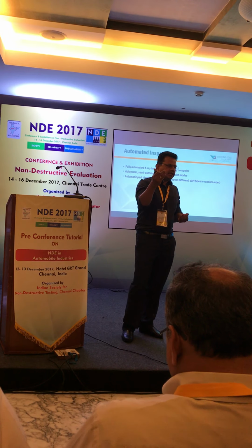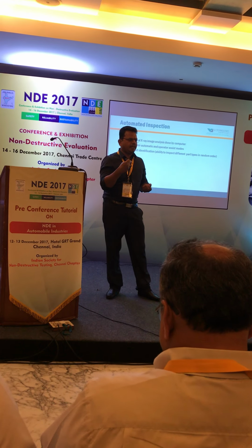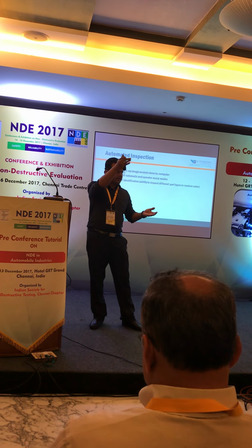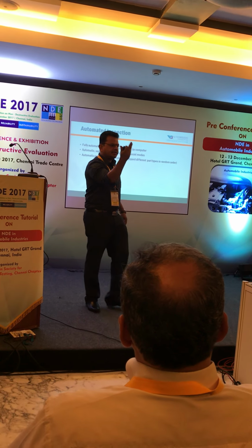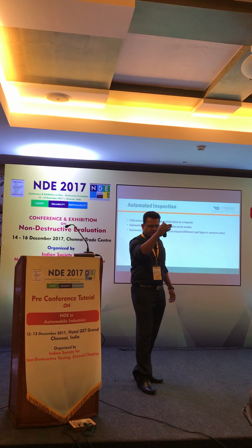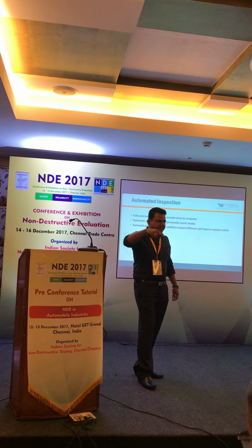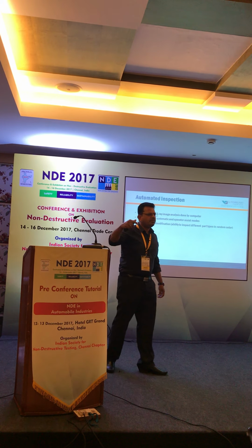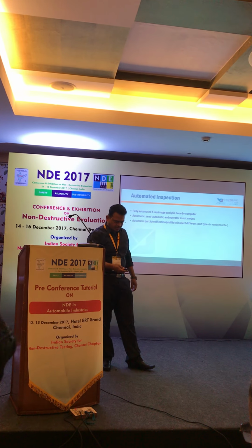When the image is taken, the process should be so fast to maintain the cycle time. Say for example, a knuckle has 5 views. If I can cover this part in 5 views, the software takes the 5 views and stitches them. As soon as it starts stitching, the first view is sent to the ADR, and the ADR sees the defects, and then the second and the third. So the ADR sees defects view by view and then gives the result whether it is accepted or a failure.